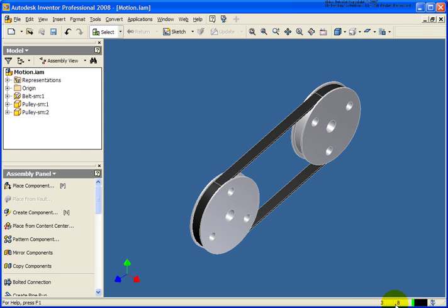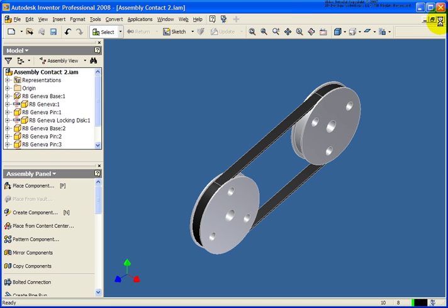And you'll see in this case, it's at the number 8 because we had 5 components from the last assembly, and it's 3 components in this assembly. So as you can see, the number of components are being added from window to window. So if you have 10, 15 windows open, each of those are going to be taking memory. So only keep the files open that you're going to be working with.